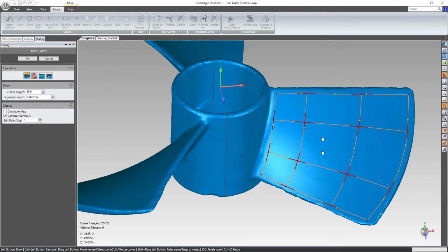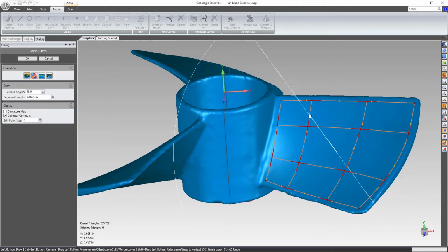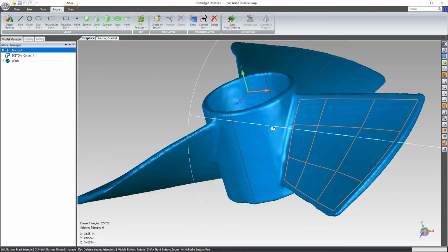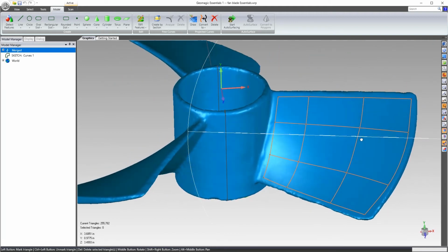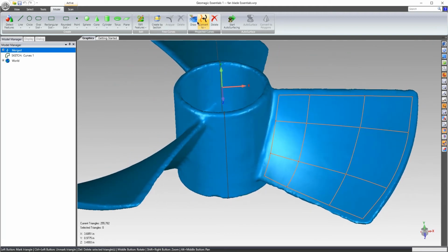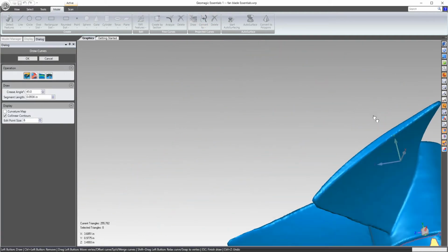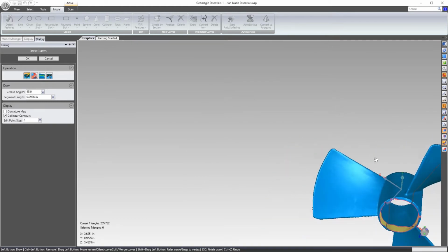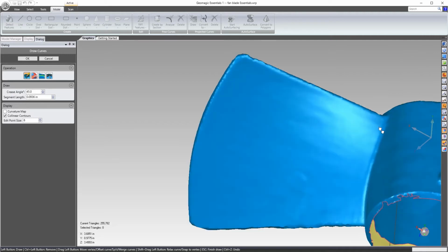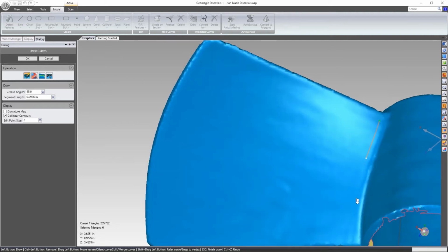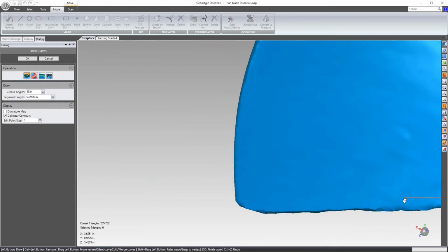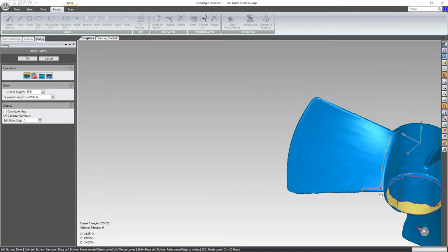So these are just to give me enough resolution to draw them inside of Solid Edge or convert them inside of Solid Edge. So you can see that I went ahead and I selected those curves and I drew them. Now, actually, let's go in and draw them on the other side, because this isn't necessarily a constant thickness blade. If it was, I would just draw one side and offset the surface that I use, which, many of the companies that make these, they all know when they're designing it whether it's supposed to be an offset or a constant thickness blade.